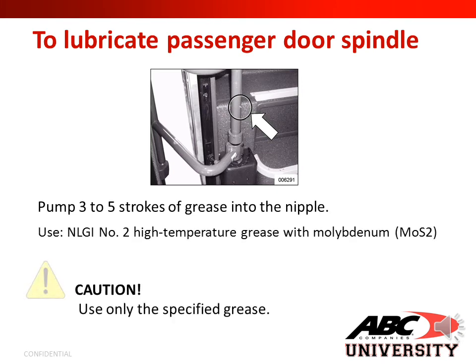To lubricate passenger door spindle, pump 3 to 5 strokes of grease into the nipple. Use NLGI number 2 high temperature grease with molybdenum MOS2. Caution: ensure you use only the specified grease.